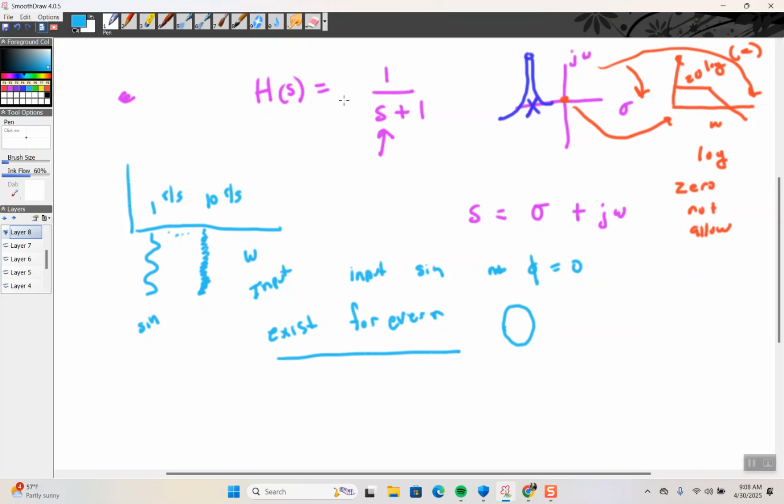All right. And then just to bring it back to the expansion, here's a 50% duty cycle, and we're saying it repeats forever. Then we get a spectral analysis where this was 1/2 because it was 50%.